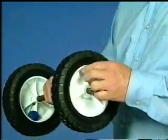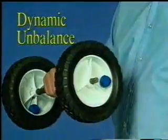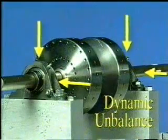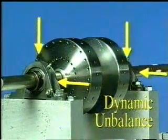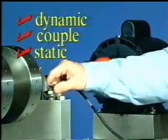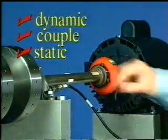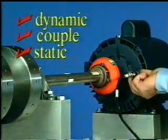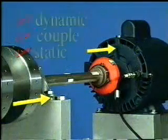Any combination of static and couple unbalance is referred to as dynamic unbalance. The phase change from vertical to vertical or horizontal to horizontal could be any combination depending on the amount and location of the unbalance. For dynamic unbalance, couple unbalance, and static unbalance, the axial readings across the coupling should be in phase. Again, in phase is normally considered to be within 30 degrees.